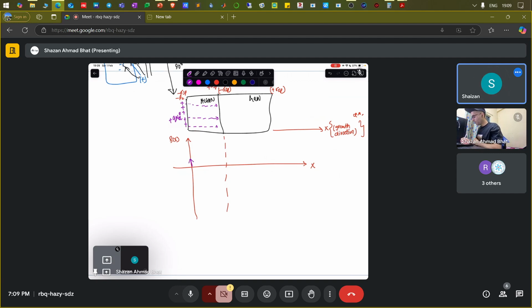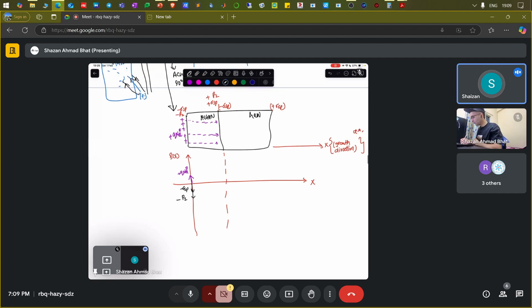You have first plus Q times Nd, which is the donor charge. Just try to follow the color code. And then you have a negative charge because of spontaneous polarization of the AlGaN and because of piezoelectric polarization of the AlGaN. And you have again here a positive charge, both because of piezoelectric polarization and spontaneous polarization of the AlGaN. And you also have slight negative charge. Let's consider it as negligible because that has been shielded, as we are considering this layer to be thick enough.